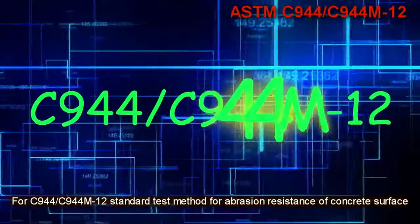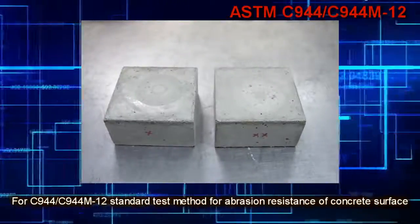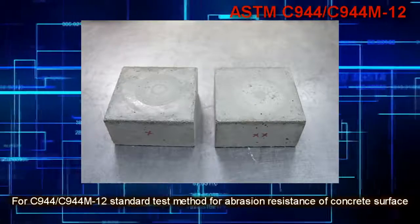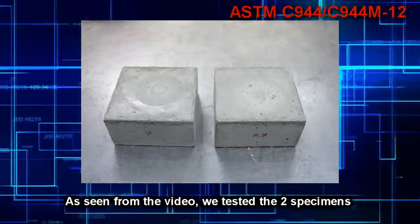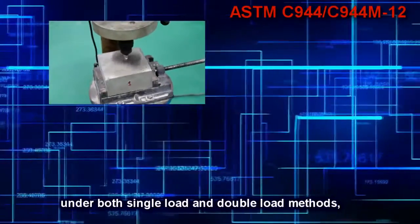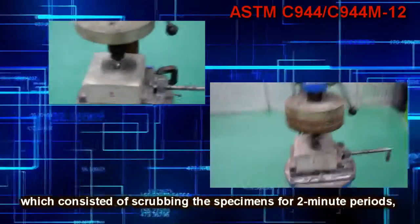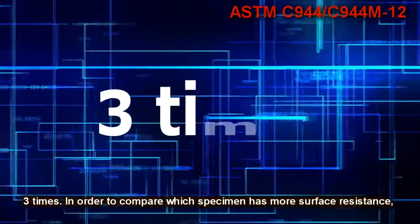For ASTM C944, the standard test method for abrasion resistance of concrete surface. As seen from the video, we tested the two specimens under both single load and double load methods, which consisted of scrubbing the specimens for 2-minute periods, 3 times.